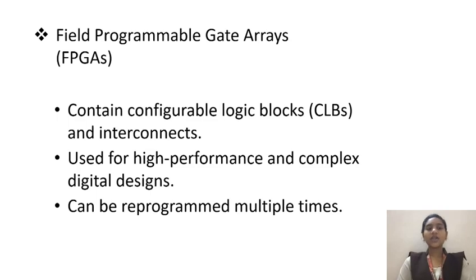Coming to the third type of PLD, field programmable gate arrays, FPGAs. So this contains configurable logic blocks, CLBs, and interconnections between the circuits. It is used for high performance and complex digital designs, and it can be reprogrammed multiple times. As we have seen, the earlier PLDs can be programmed only twice or thrice, but an FPGA can be reprogrammed many times, as many times as possible. This is the advantage of FPGAs.